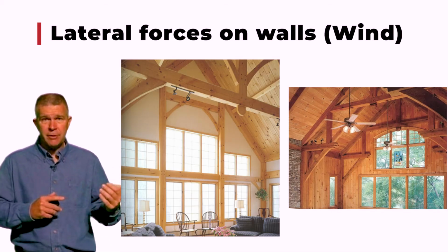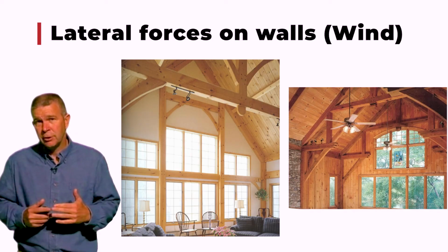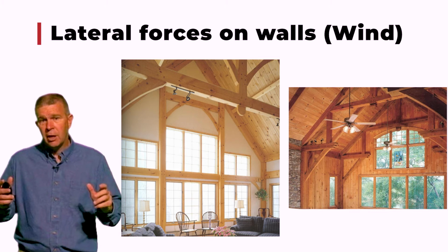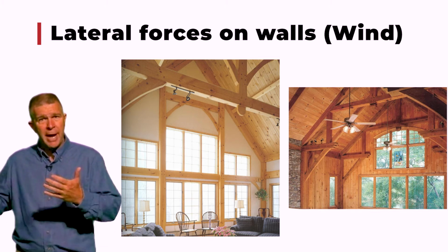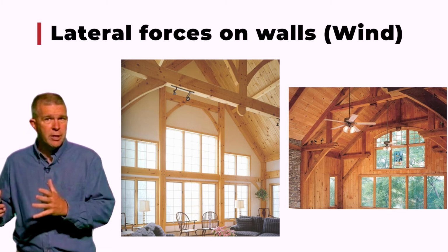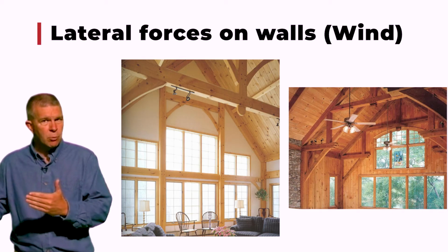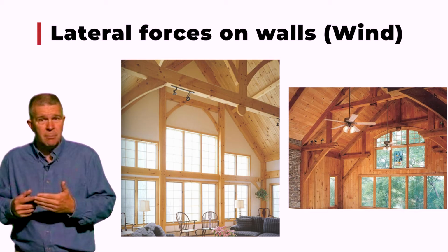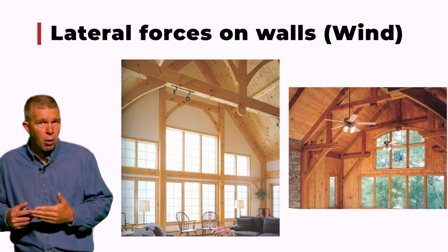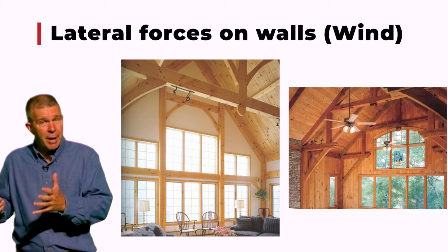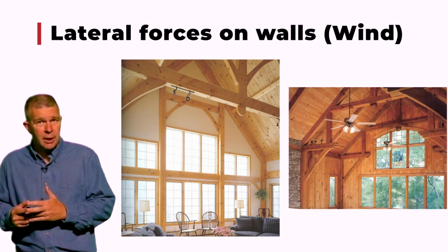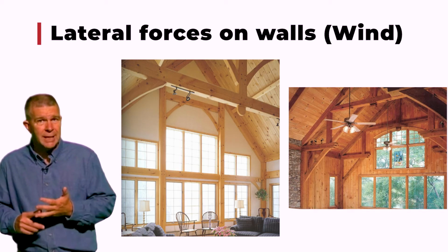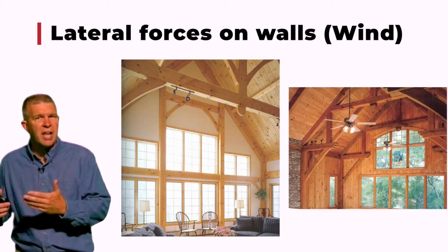The one on our left, the one on my right doesn't do a very good job. Now both of these pictures are within timber frame structures, but again, the one on the right puts a big dramatic tall wall with a whole bunch of windows in it with no good way to resist the force, which is that wind. Now this panel is being asked to do an awful lot of work, and in essence, as the designer starts to calculate those loads, it may require you to put a lot of lumber or maybe even steel inside of this wall panel to resist that force.